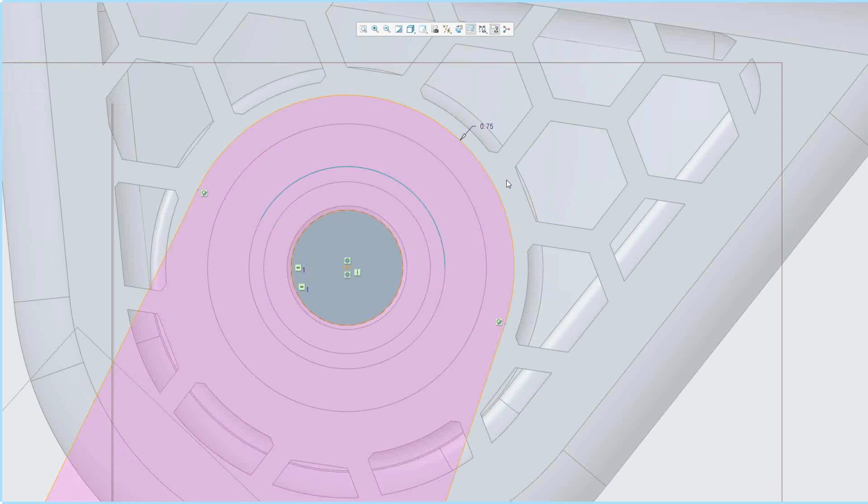Yes, you can remove external references much easier, or you can even prevent external references from even being selected in the first place. If that's your design intent, you can do that from your config.pro. But yes, this method will allow external references to be selected if you just go ahead and use it. This is basically almost how all of Creo has worked so far.